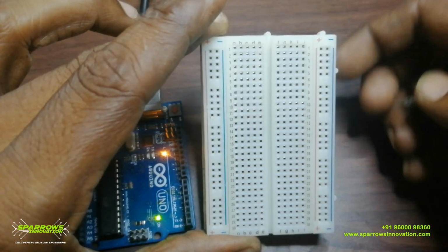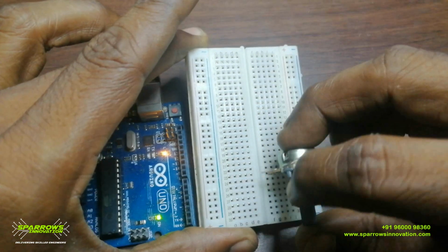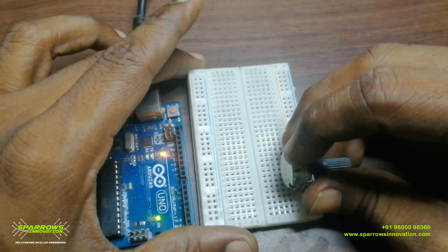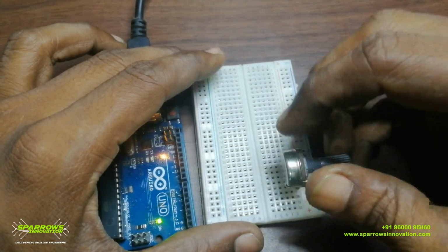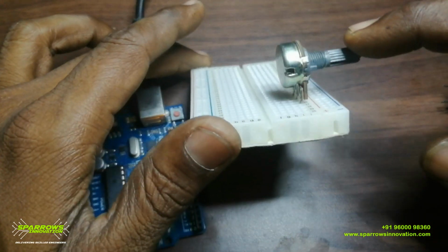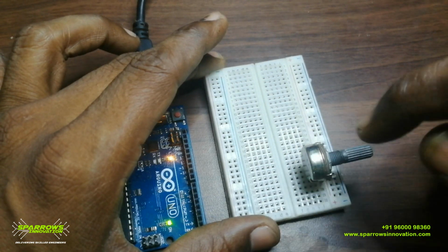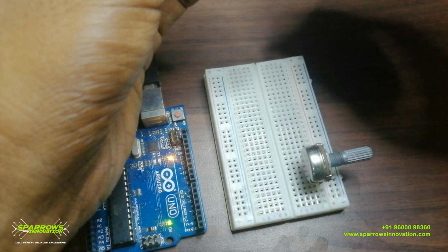You can see the numbers present in there. So you have to place your potentiometer in vertical direction, not in the horizontal direction. If you place it in vertical direction, the 3 pins will be separate pins. If you place it in horizontal direction, the 3 pins will be short circuited, right. So I place the potentiometer like this, vertically. So I can give 3 wires for my 3 pins respectively for giving the connection to my Arduino.